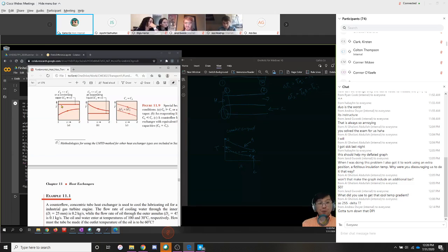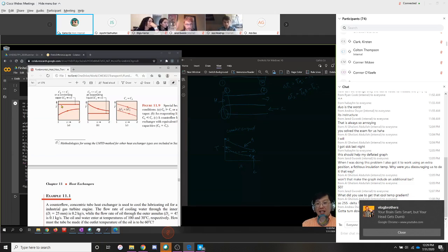What does that mean? Well, there are two possibilities. One of them is that you've got a phase change situation, right? Let's say you have steam that is condensing. The bulk temperature of the steam that is condensing is, in that case, governed entirely by Antoine's equation, right?